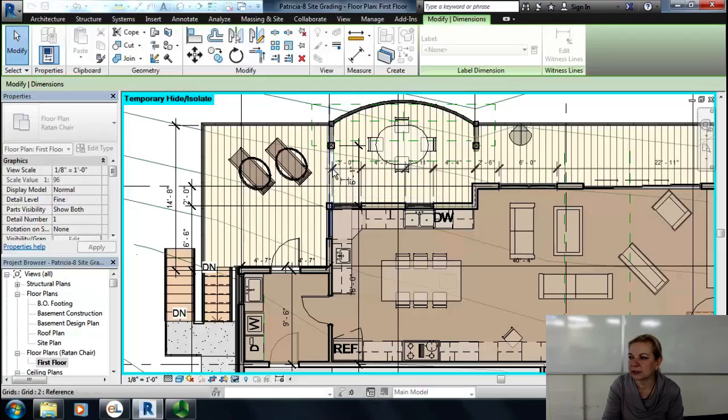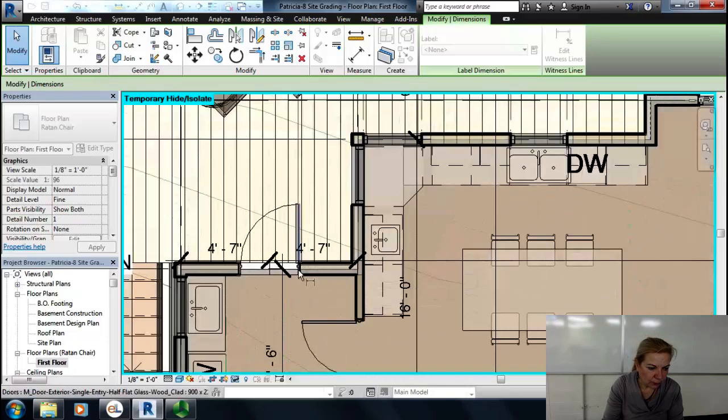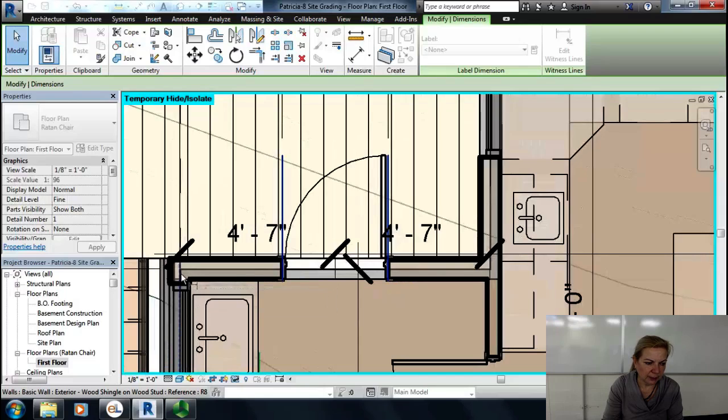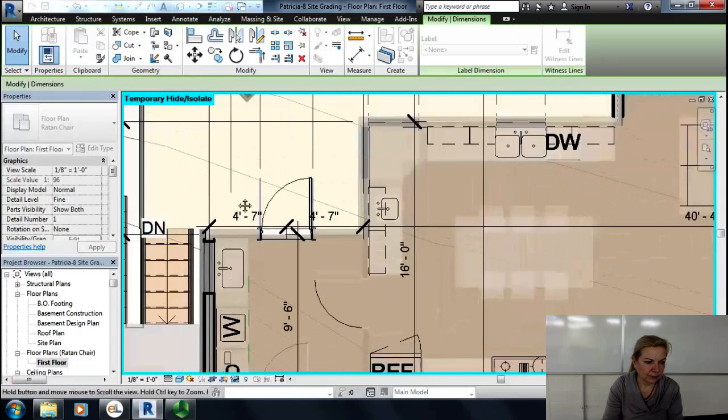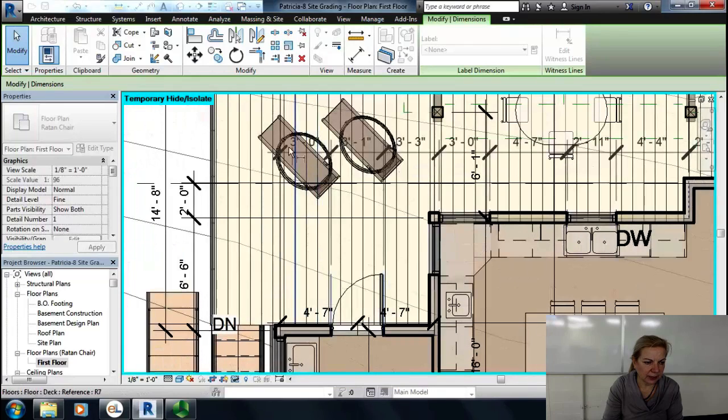And in the video we watched yesterday, remember that you can also set under options that pop out here how you want the dimensions to be picked. You can go to center lines of openings. I have it set for openings. So I'll keep going into dimensioning my door. And I have my lines now set on, and watch for those blue lines coming up. Revit knows what you want to dimension, but you want to make sure that you're picking up the right content. And watch that you actually have created the dimension.